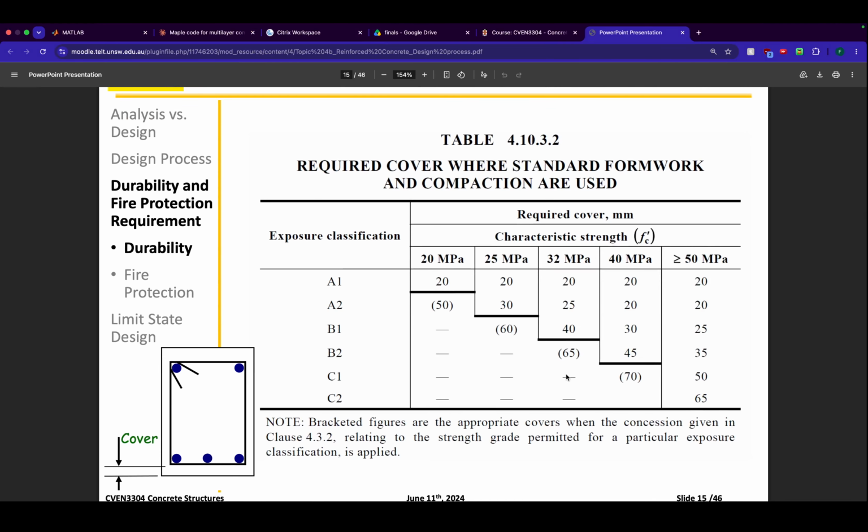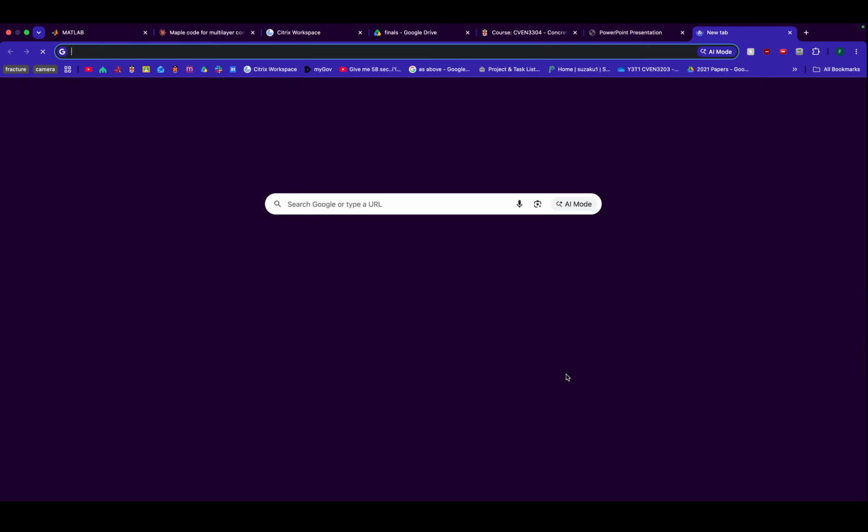It's the distance from the steel bar. They have a diagram right there. This is also steel, yes. That's part of the steel. Remember the hooks and cogging and stuff that I was talking about? There are two kinds of reinforcement. You've got your primary reinforcement to prevent bending, tension failure, all that kind of stuff. But if you want to prevent shear failure as well, you need a different kind of reinforcement. That's not yet, it's covered in shear.